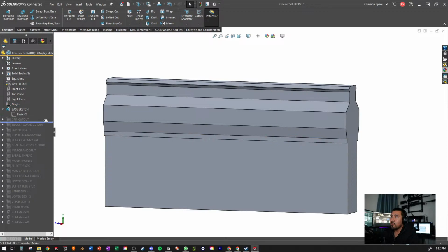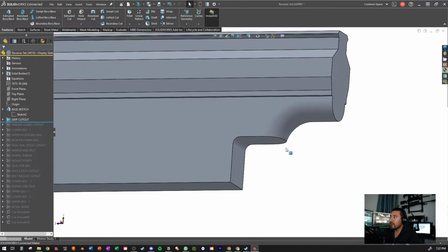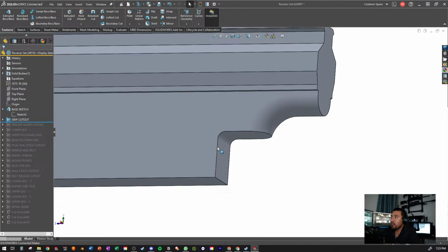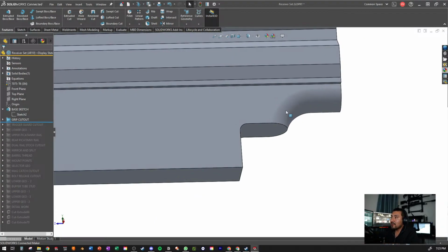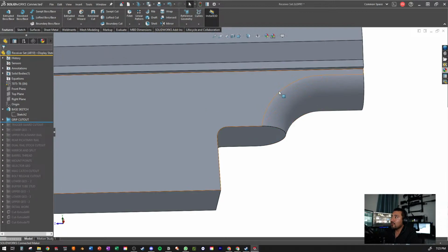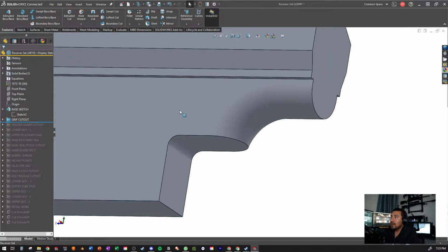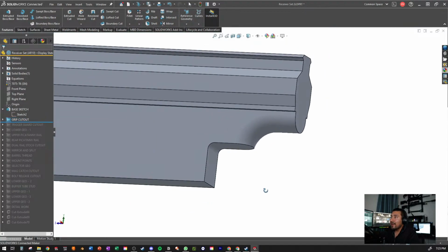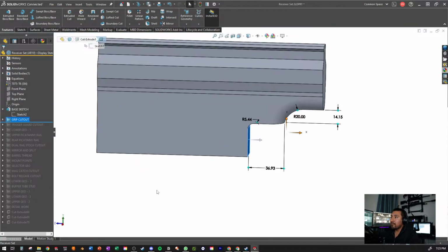It was that important. And here's the grip cutout, getting this geometry just right so you could fit onto that grip, because that's probably one of the most complex portions of the design. So I made it very apparent to tackle this first, so I could get the rest right. And I used these two planes as my driving planes for the entire rest of the design.